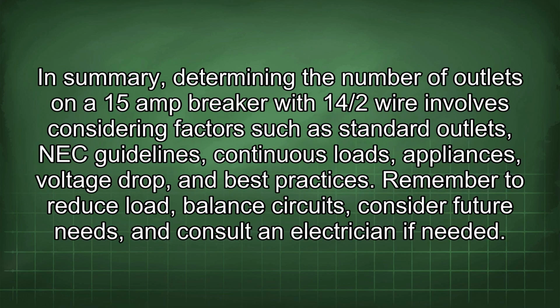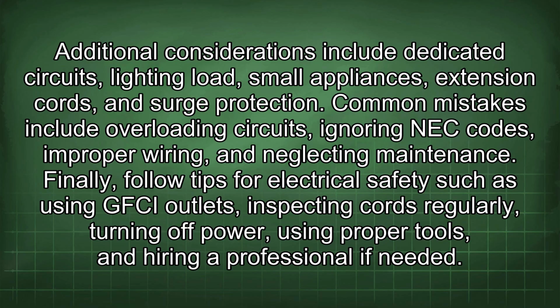In summary, determining the number of outlets on a 15-amp breaker with 14/2 wire involves considering factors such as standard outlets, NEC guidelines, continuous loads, appliances, voltage drop, and best practices. Remember to reduce load, balance circuits, consider future needs, and consult an electrician if needed. Additional considerations include dedicated circuits, lighting load, small appliances, extension cords, and surge protection.